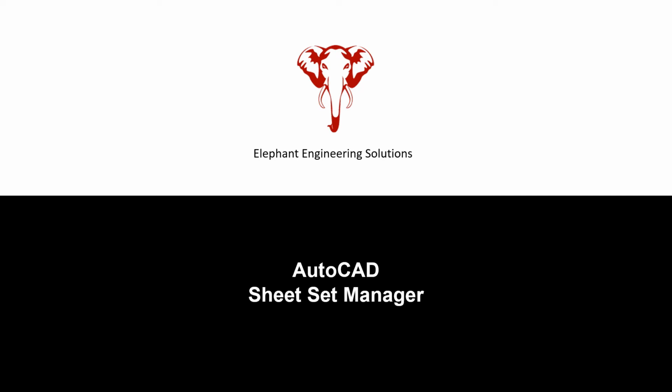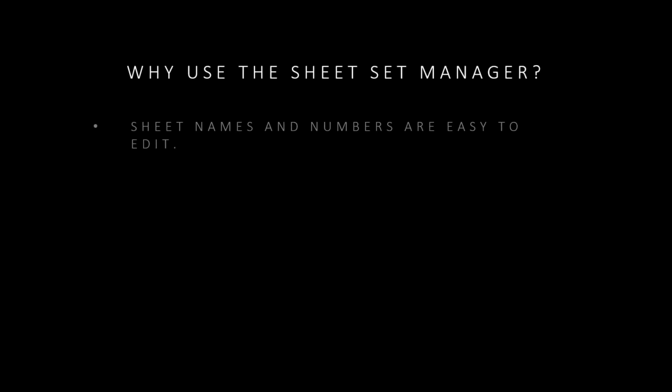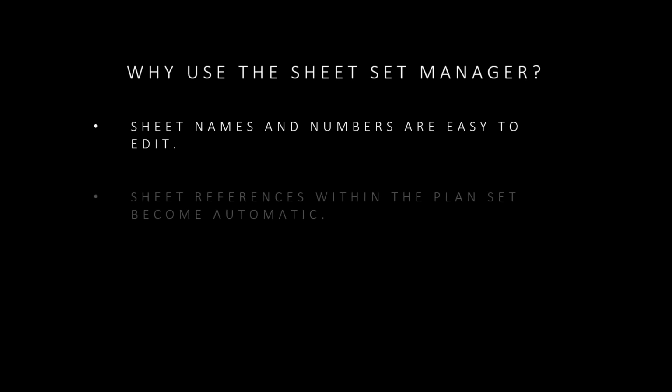Today's video will cover setting up and using the Sheet Set Manager. The first question we should ask is, why use the Sheet Set Manager? The first reason is your sheet names and numbers can be handled through the Sheet Set Manager. The second reason is references to other sheets within the plan set can be set up as sheet set fields and edited through the Sheet Set Manager.